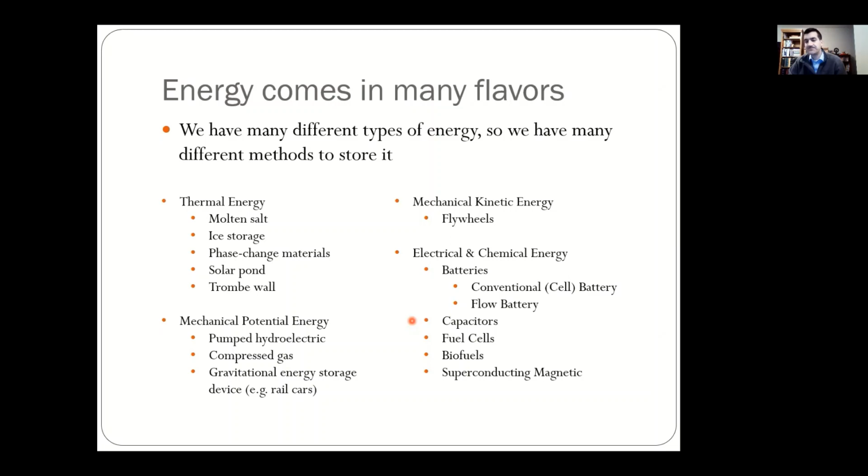Capacitors, I'm not going to say a whole lot about that. Basically, they store energy in the form of an electric field. And you can get power from them very rapidly. So their power density, the amount of power that you can get per, say, unit volume or per unit mass, is pretty good, but their energy density is poor.